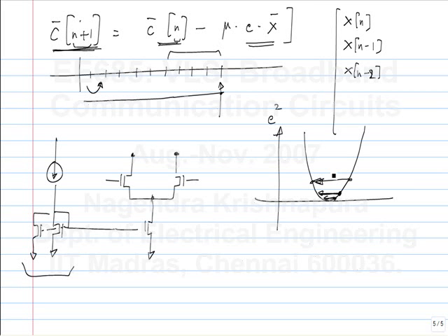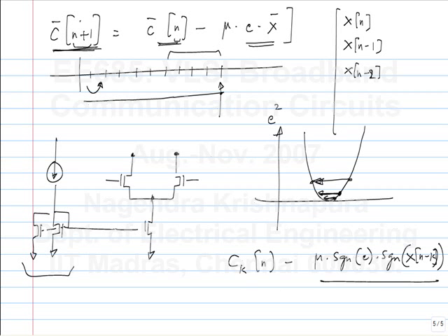So I shouldn't say how would you reduce the value of mu, but how would you reduce this chattering around? Because if I implement this, this is the equation I will implement for the coefficient Ck update. Now this coefficient will be changing in every step because I get some sign for E and some sign for X. I mean, not constantly increasing or decreasing, but each step it will be bouncing around. How do you reduce that?